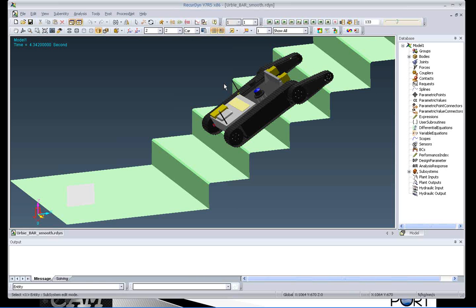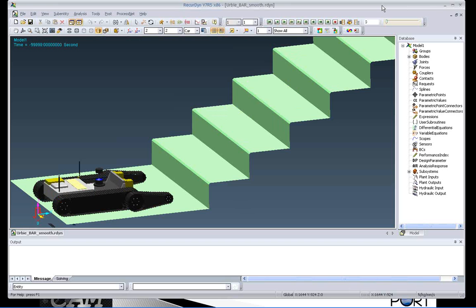And then as you develop new variations of the product, your simulation techniques will be accurate enough to really do some predictive work with regards to loads and to have a good amount of confidence. Okay, so that's kind of the philosophy of how to get a good system for getting the right loads to then import into FEMAP in order to do the component analysis.